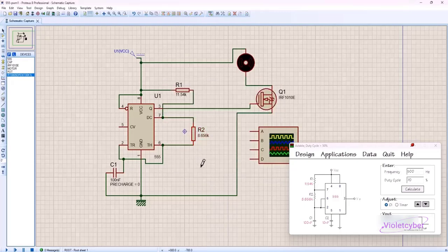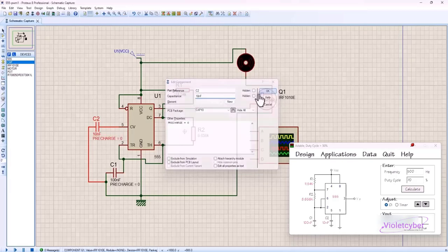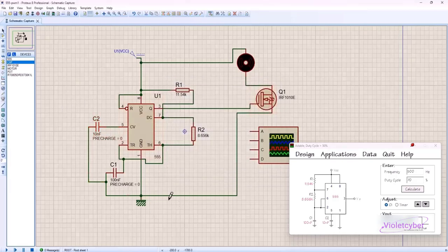And we connect pin 5 to the ground with a 10 nanofarad capacitor. That is, we put the 10 nanofarad capacitor here. You want to connect pin 5 to it, and on the other side that connects to the ground, this is also 10 nanofarads. We will also do this 10 nanofarads and okay, and I think there is no problem.